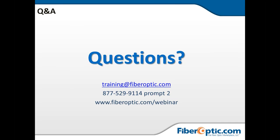And one quick pointer: if it fails in one direction and not the other, say it passes A to B, but B to A fails, B side is your dirty connector, because it's going to have a much larger impact close to the transmitter. So whichever side fails, that's your dirty connector. Go clean it.